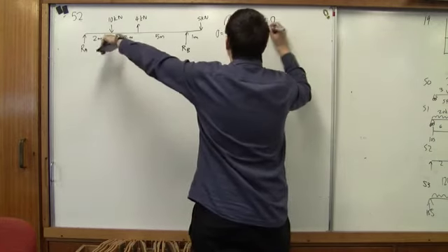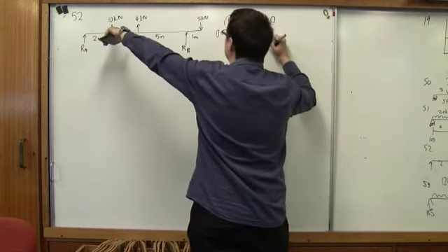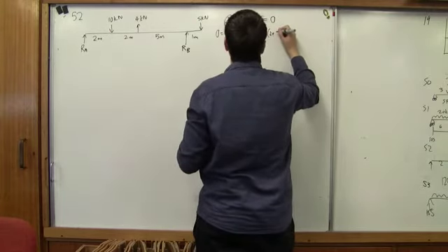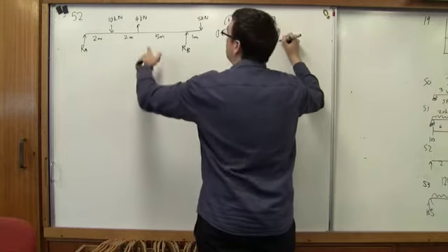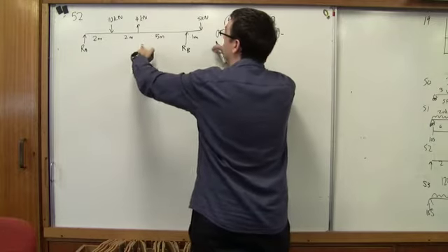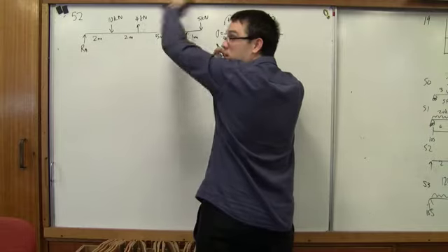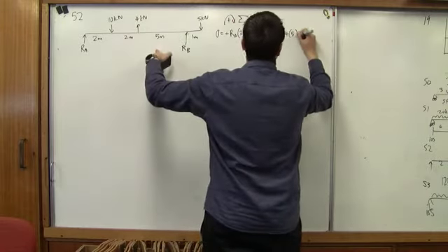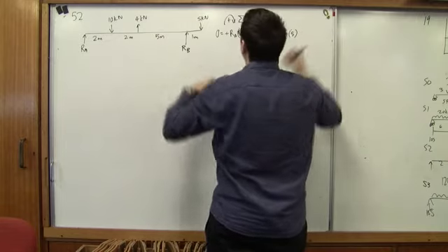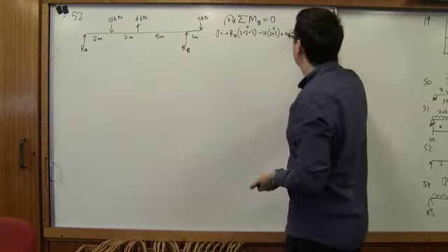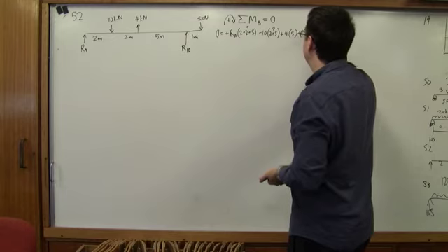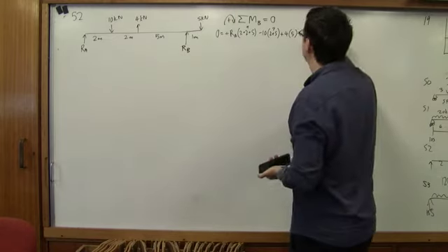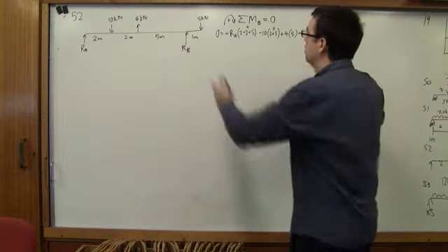So this one here, 10, is it going clockwise or anti-clockwise? Anti-clockwise. Okay, and its distance is 2 plus 5 is 7. And then the next one we have is 4. Is that going clockwise or anti-clockwise? Clockwise, multiplied by 5. And then RB. Normally I'd write RB equals 0, but I just write here RB times 0 because it's 0 distance away.